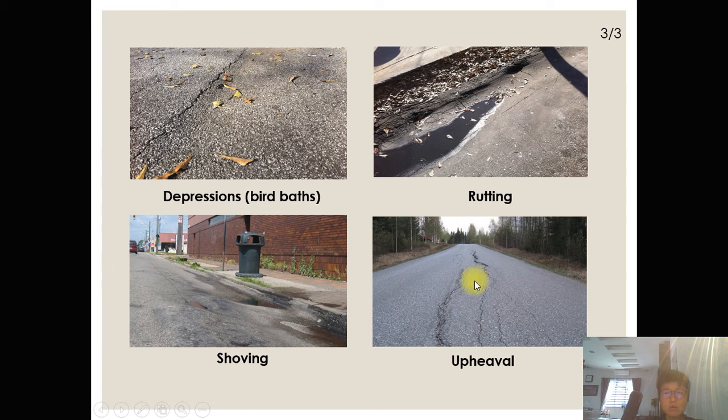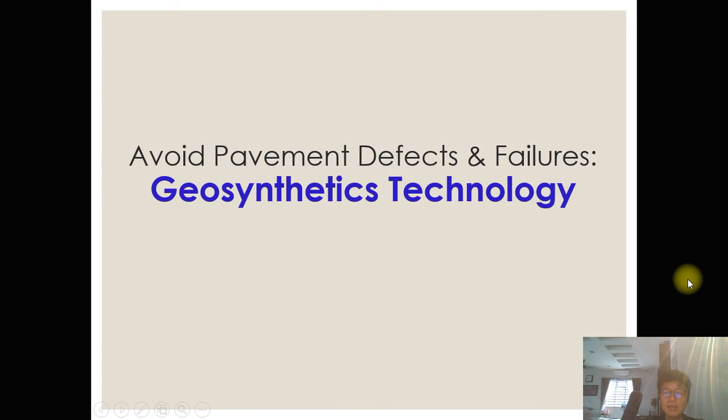This situation is most probably because of the frost. Yeah, it's heaving the road. And if it is not due to the climate, because of the low temperature, it could also be due to the soil down there that is expansive. We learned it in some mechanics, expansive soil can also cause upheaval of the pavement.